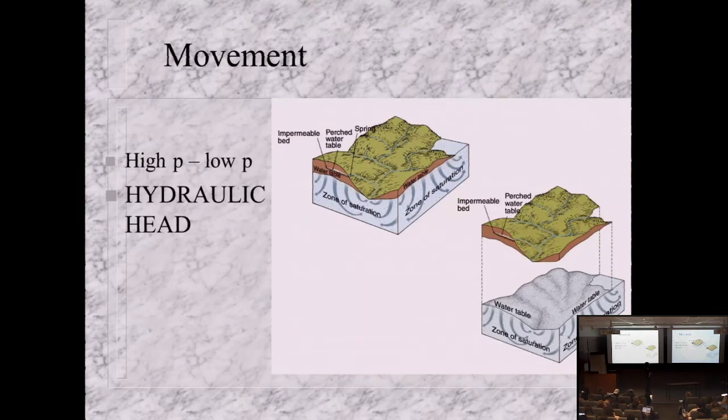And so what you're seeing here, you can't ever obviously really scrape off the surface of the unsaturated zone. What you see here is that there is a river system, and you have high points on the landscape, and then you have low points. And what we typically say about groundwater is it's a subdued replica of surface topography. So what that means is that the highs aren't as high, the lows aren't as low. So you see that groundwater is doing, if you pull off the unsaturated zone, the same thing that the land surface is doing, but again, the high is not as high at the highest point, and that is a recharge area. Water is going down from the land surface and recharging the groundwater.